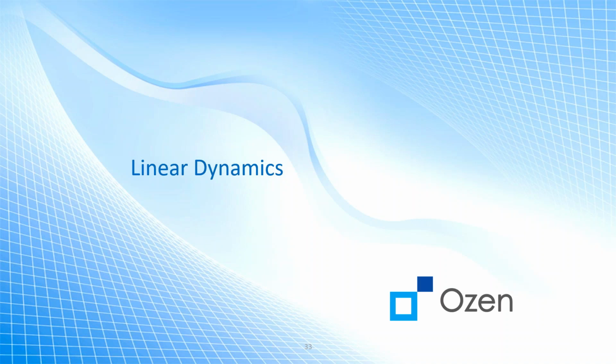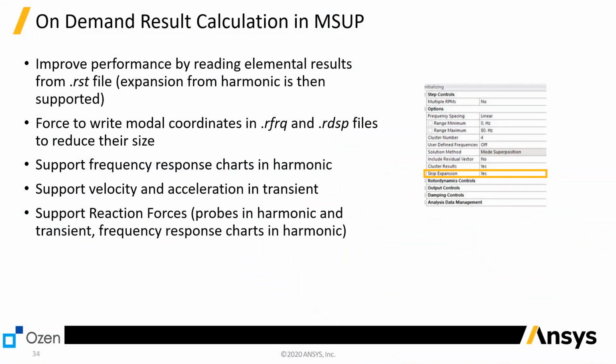As I said, I'm not showing everything because there is tons of it, and we are limited on time. So I will now move to linear dynamics. When we say linear dynamics, we're talking about harmonic analysis, transient analysis, modal analysis. In linear dynamics, some improvement is related to reading the element result directly from files. Now we also support frequency response charts in harmonic, velocity and acceleration in transient, and reaction forces based on probes in harmonic, transient, and frequency response chart in harmonic as well.